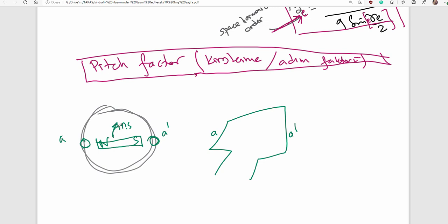If it rotates in clockwise direction, here's cross and here's dot, so polarity of EMFs will be like this, and the induced electromotive forces of side A and side A prime will be summed together and make EAA prime. That is the perfect summation.